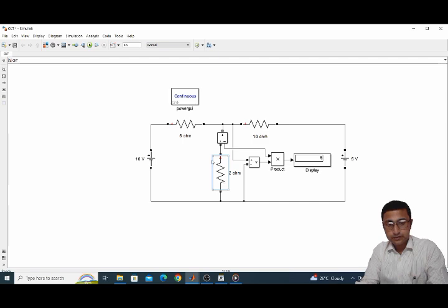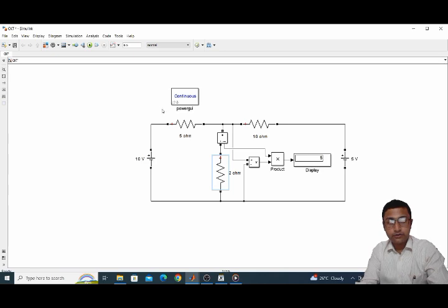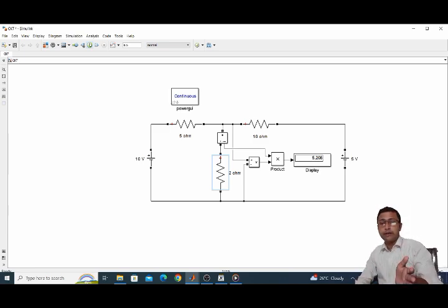Then if I put the Thevenin resistance here, that means 50 divided by 15, and run the simulation, it shows 5.208. That means this is the maximum power, by putting the load resistance equal to the Thevenin equivalent resistance. So your theoretical calculation is again validated in the simulation platform. This is the procedure of solving a network using Thevenin's theorem and the maximum power transfer theorem.